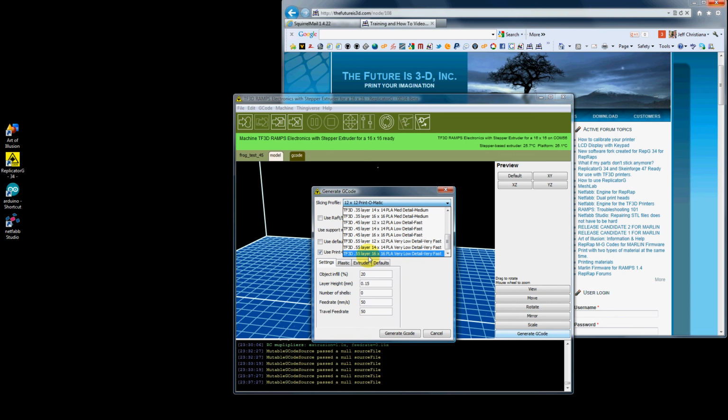I've got a printer right now that'll do up to 27 inches in build height. So we're looking at doing like a 1.5 layer height, so you can really make some large objects when you don't really need this fine a detail. If you tried to print something that big with 0.15, your machine would just shut down. There's so much G-code that it needs, so many layers. It's crazy. So let's take an object that's an inch tall, if we do it at 0.55, it takes 100 layers. If we go down to 0.15, you're probably talking about 1,000 layers.